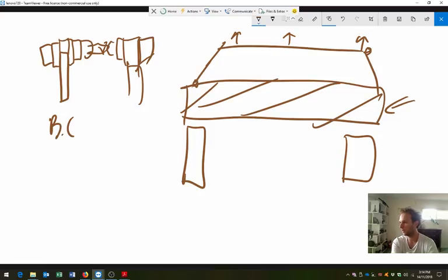All right, cool. Could you summarise the main properties of Coode Island silt? Yeah, relatively low permeability, very reactive material. Its permeability horizontally is greater than that vertically because it's built up in layers, and it's got quite a lot of organic material in it. So you've got little bits of seashell and all sorts of stuff. So low permeability, very weak material as well. So weak and reactive.